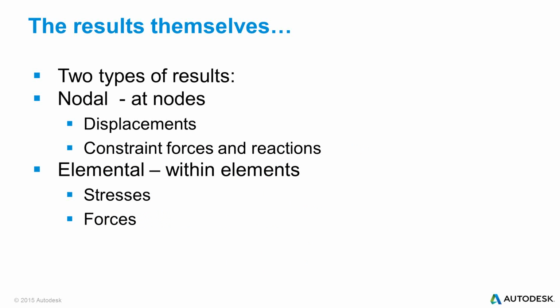There are two types of results that come out of Nastran or that are available in In-CAD, and those are nodal results. By nodal results, we generally mean quantities that are calculated at the nodes. Displacements, for instance, are always calculated at the nodes. Constraint forces are always calculated at the nodes.